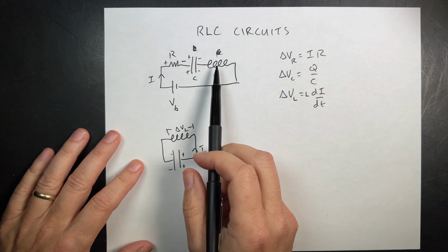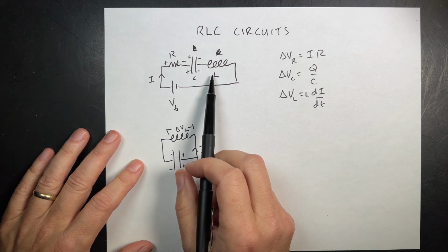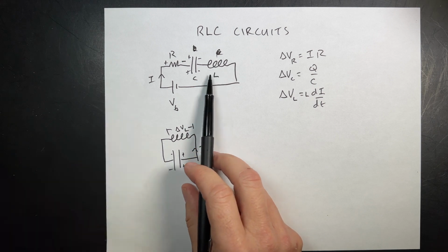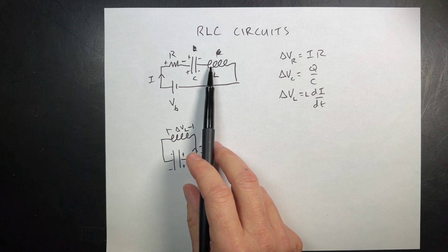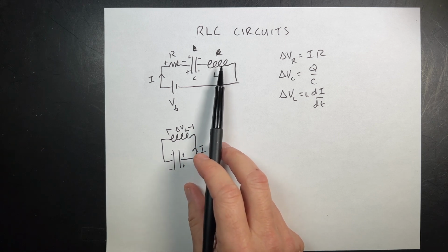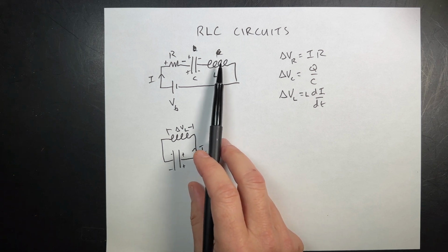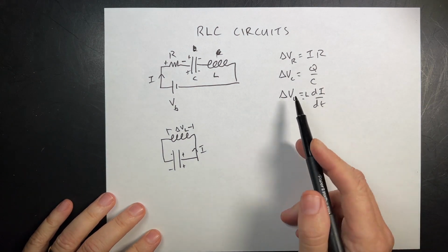The voltage across an inductor is proportional to the rate of change of current, right? Because what happens here is that you have these coils of wire. When the electric current increases or decreases, you change the magnetic flux through these other parts, which creates a curly electric field that creates a back EMF. So it always opposes the change, and that's why there's a negative sign there, but I'm just talking about the magnitude.